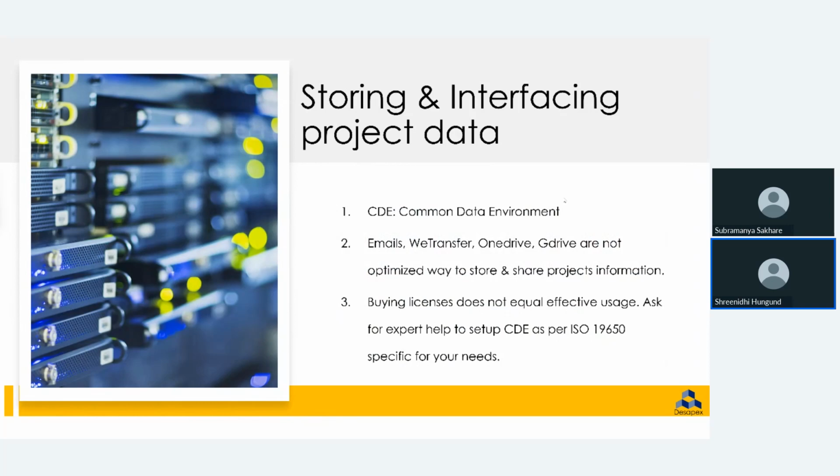For example, if somebody has approved a particular drawing and that approval is not in our common data environment, and the version of the drawing has already been replaced at the construction site, but the coordination is happening on a different version. All these version-related issues, where a different drawing is used on site and in design, happen because we don't have a common data environment.